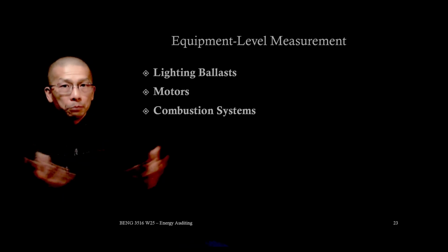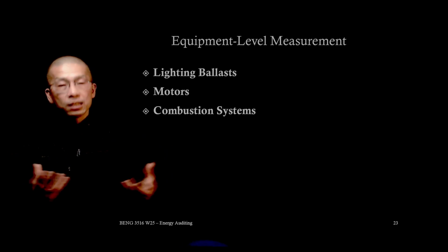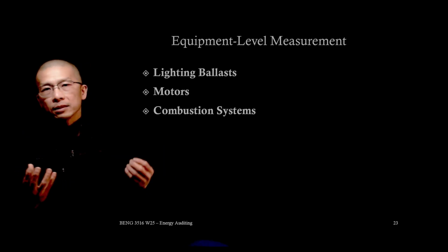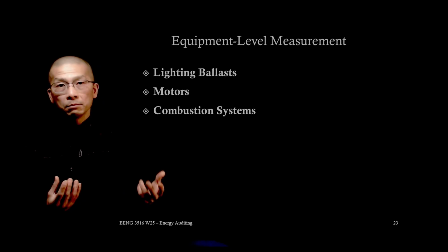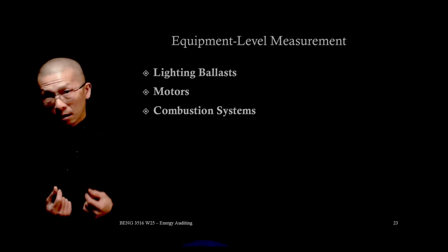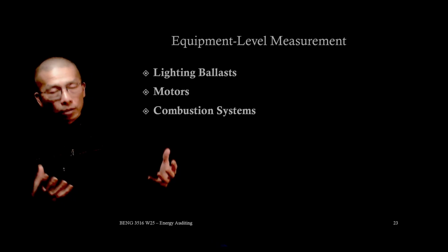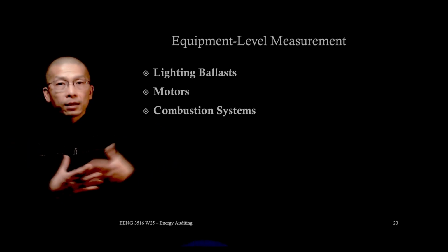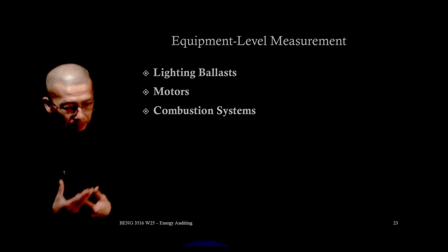Incomplete combustion means fuel not fully burned, energy not fully released and used. Then we might see, say, more carbon monoxide rather than carbon dioxide, and more oxygen, because oxygen is supposed to combine with the fuel in the combustion process. Things like that.